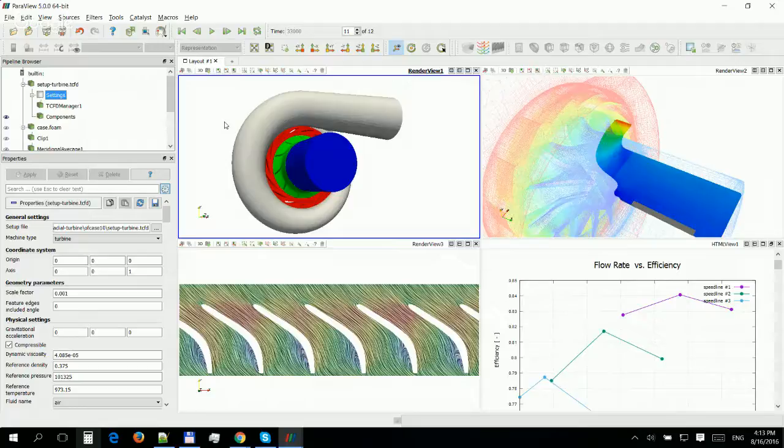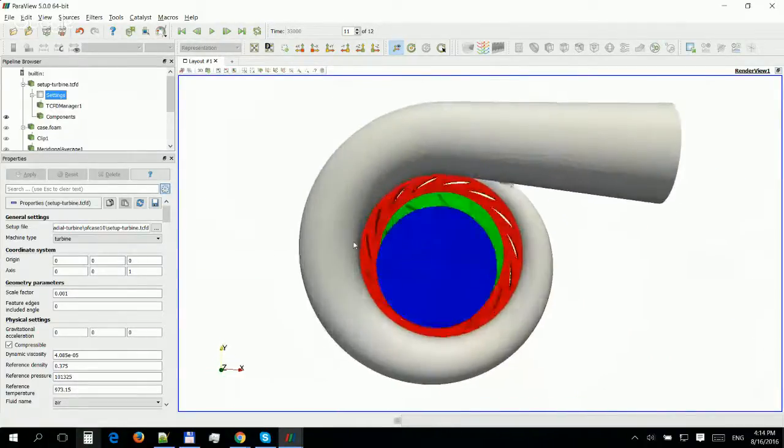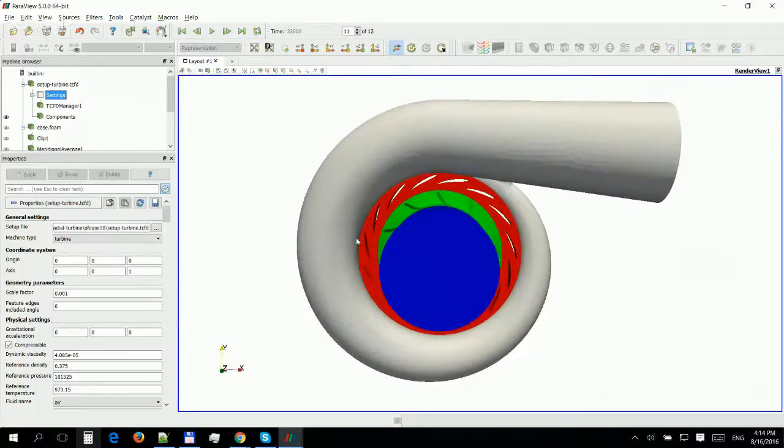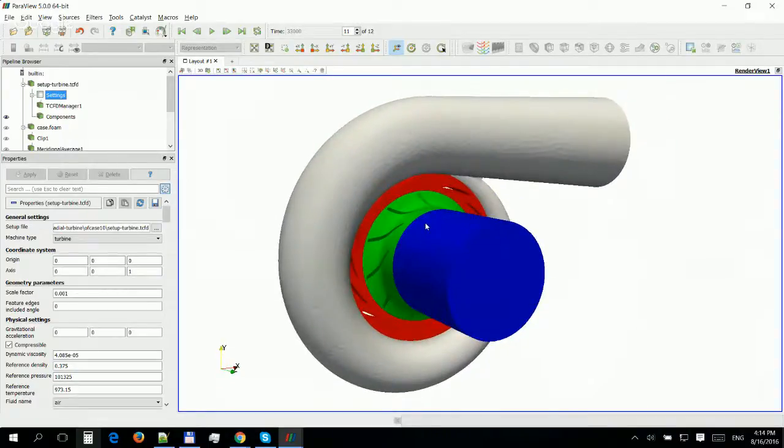And usually the aim of the radial turbine designer is hunting for pressure ratio, flow rates, torques, and of course the efficiency. So each Turbomachinery CFD simulation case has its inputs, and these are basically the surface geometry, which is 3D geometry loaded from some design tool or from your CAD, for example. It's very standard, very simple .stl, so it's stereolithography format, very standard.